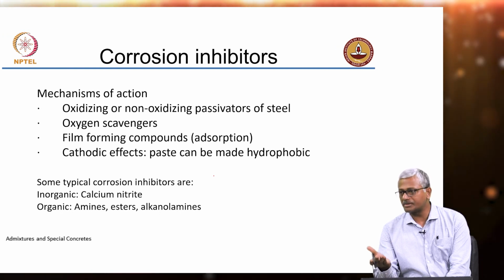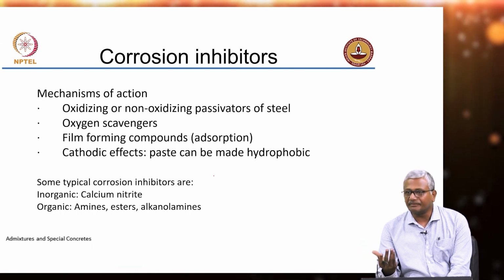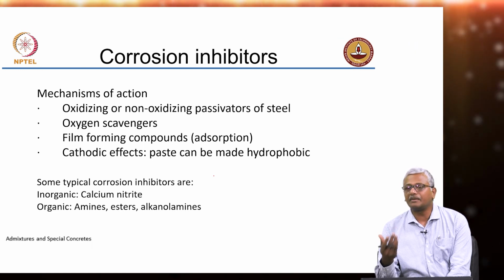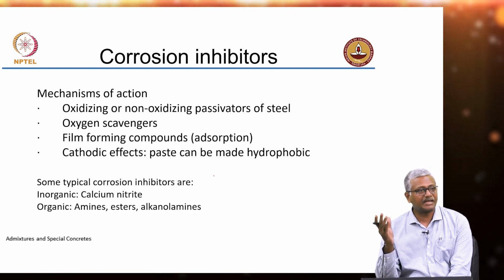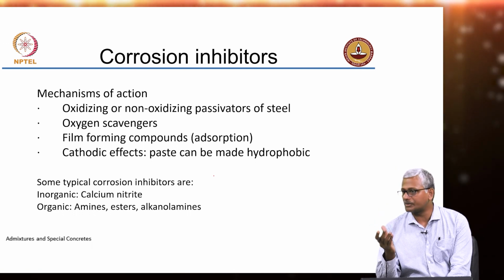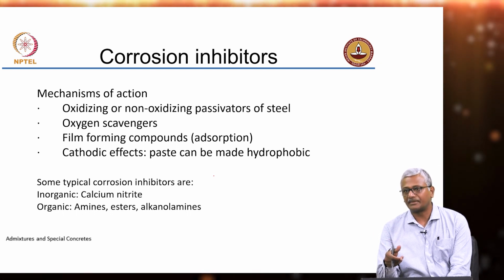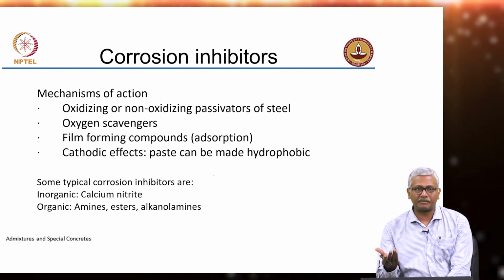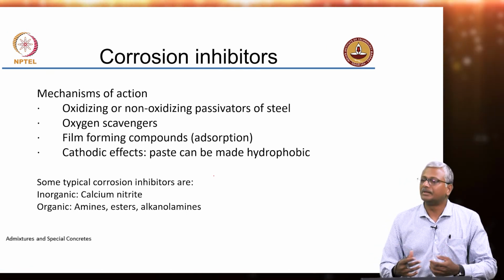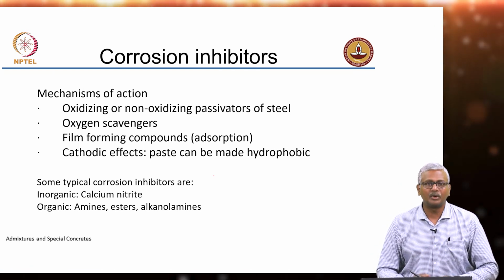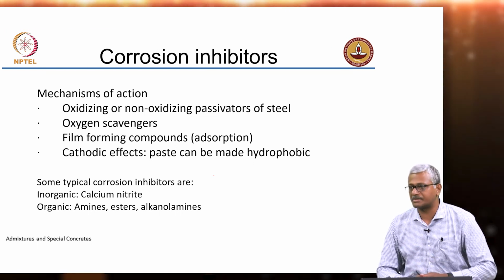You can reduce the water cement ratio of the concrete, but if you want a strength of M35, you are not going to simply keep reducing water cement ratio, because your strength may get exceeded even twice or thrice if you really want to protect the steel from corrosion at that level of strength. You have to design the concrete for its particular application. So, you can't keep on reducing water cement ratio, because your strength requirement may be simply too low as compared to what you are realistically getting for providing corrosion resistance.